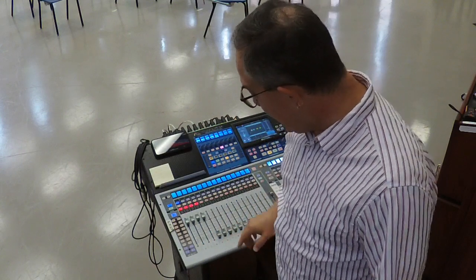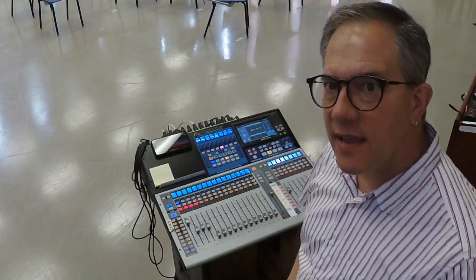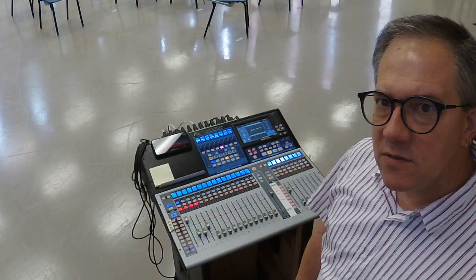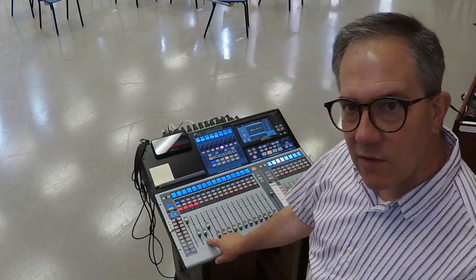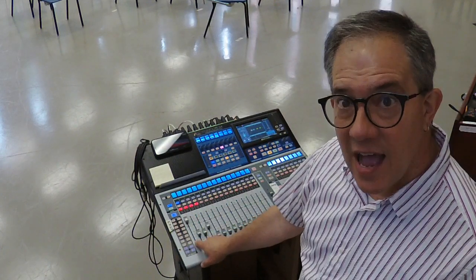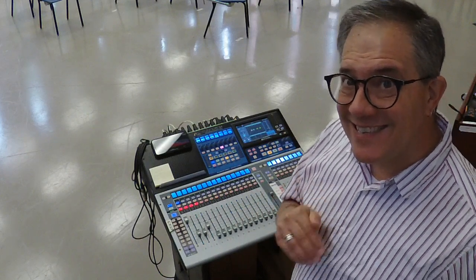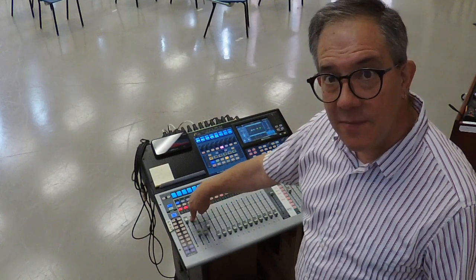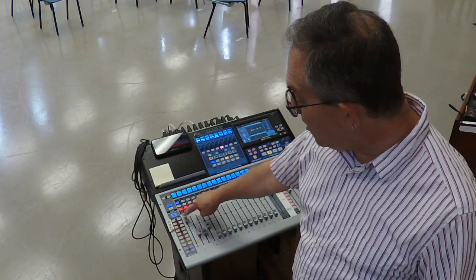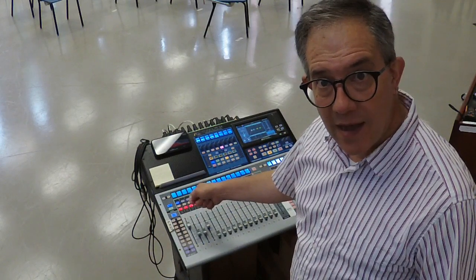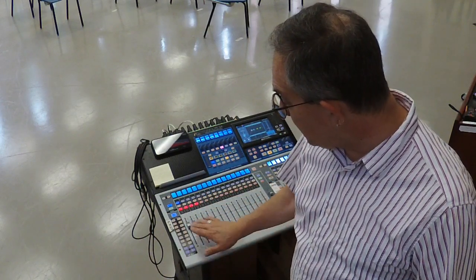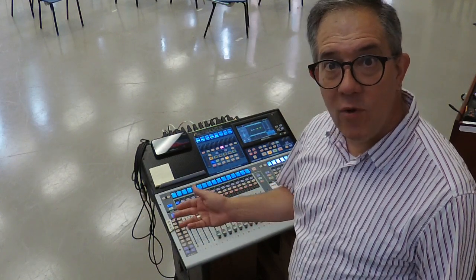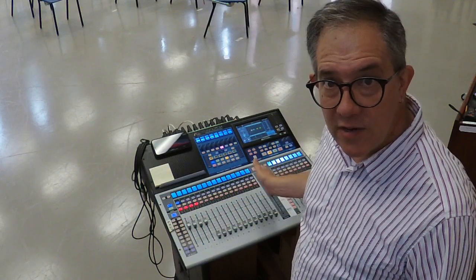What I want to look at is if I am looking at a mix and what you see is very, very offset meters. You can see where I have 2 and 3 are very low, channel 1 is very high. If that is consistently happening, I have got my preamp set incorrectly. If I have to get this high to make this correct, I need to go into that channel and turn the preamp gain up, so that for the most part, I'm in a fairly small range as I'm turning these faders up and down.